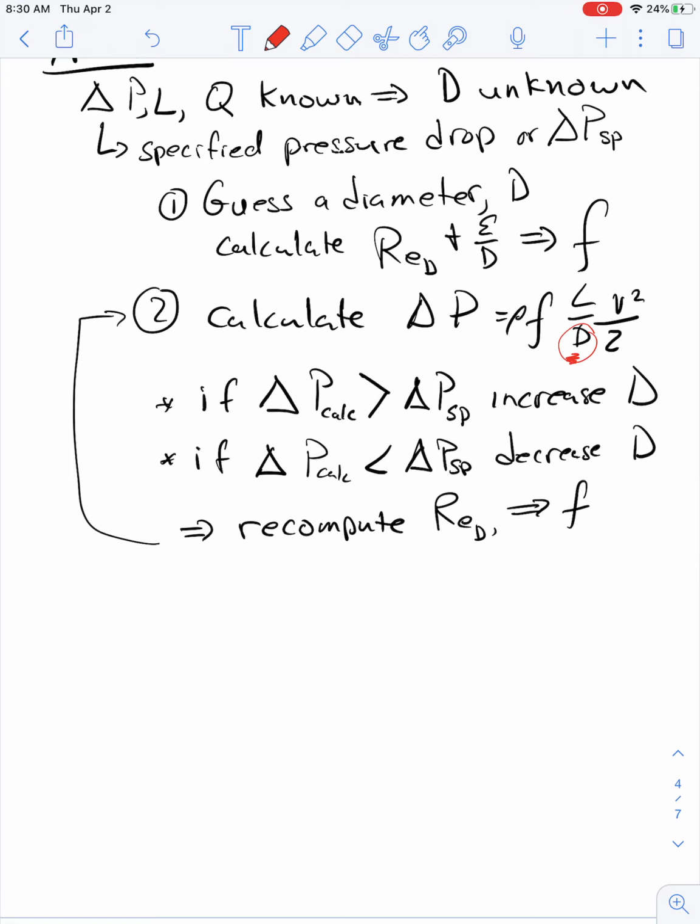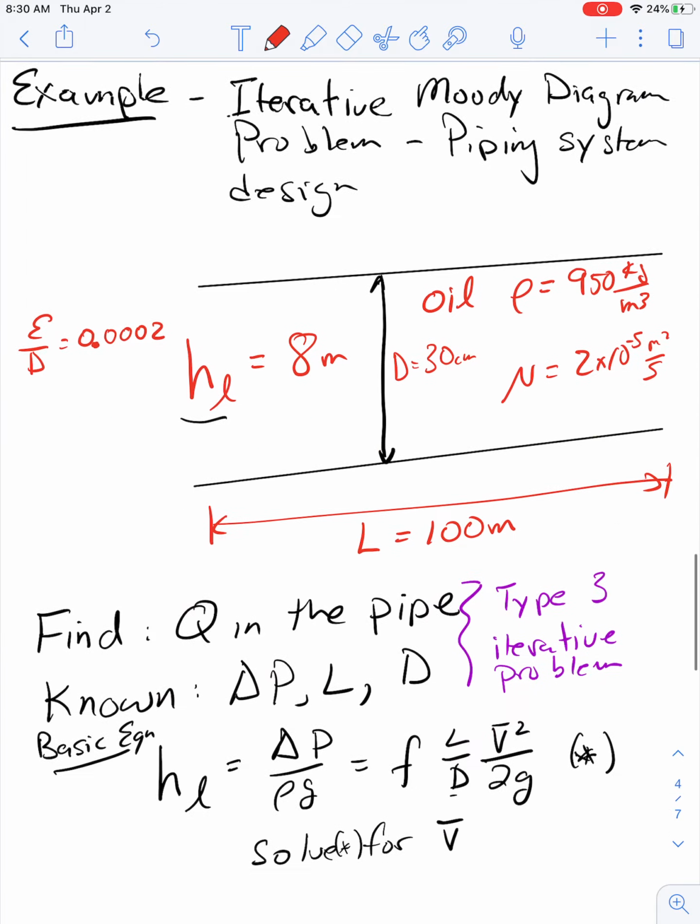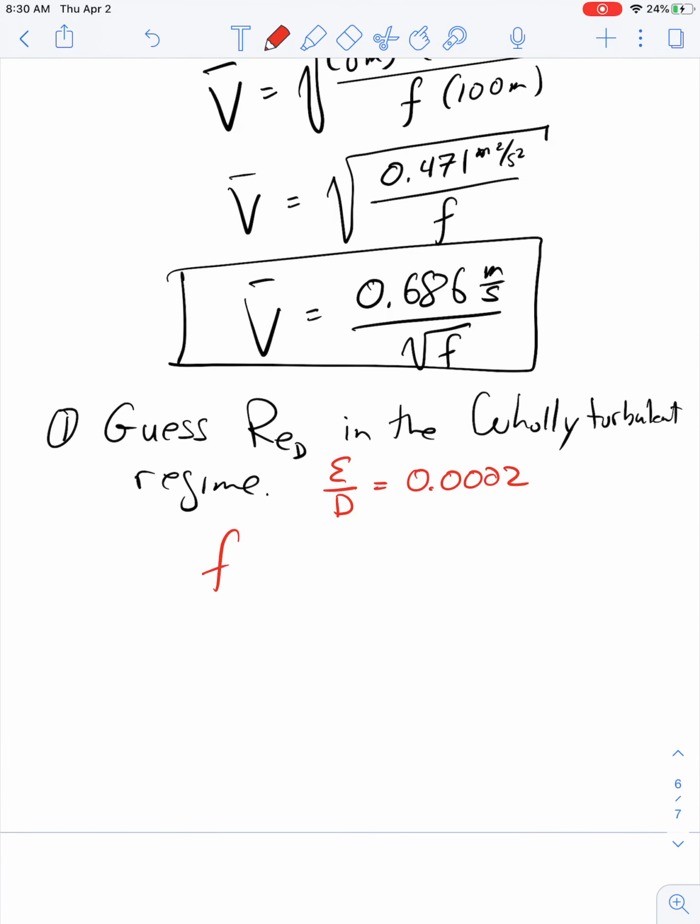All right, so we found f is about, oops, I gotta go down even farther. f is approximately, from the Moody diagram, about 0.01. And when I did it more carefully and slowly, I get 0.0135. So I maybe moved my line up just a bit and not perfectly straight, so I apologize there.